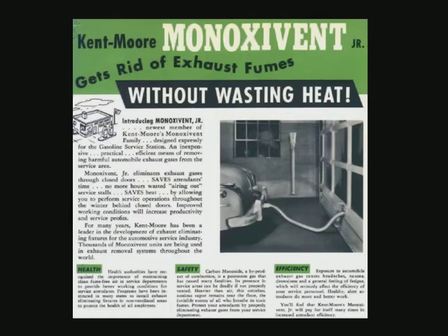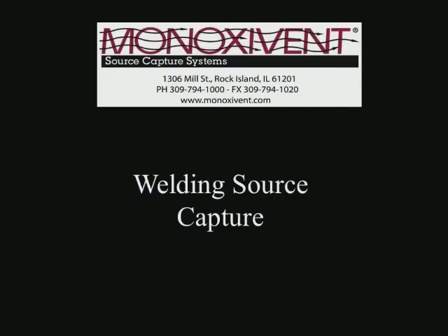What we're showing here basically is a tailpipe. So you have a tailpipe adapter on the tailpipe, you have the hose, you have the door port. And this is all under positive pressure. So it's the car or the engine expelling positive pressure into the hose environment, and that's being carried to the outside. The ideal situation for that is to keep the hose short and straight as possible. Now this picture is showing a metal hose. Again, we would recommend using our no crush hose just in case it gets run over. So with that being said, that's it for vehicle exhaust.